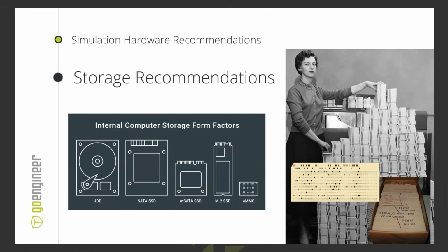So let's say you had 128 gigabytes of RAM in your system, you would need a finite element problem somewhere in the neighborhood of 60 to 120 million degrees of freedom to populate all the RAM. That's beyond what SolidWorks simulation is going to solve. So you probably have more RAM in your system than you could reasonably populate for even a really big finite element problem, regardless of the solver that you're using. Hopefully that addresses your memory bandwidth question. Right. Thank you for that, Bill.